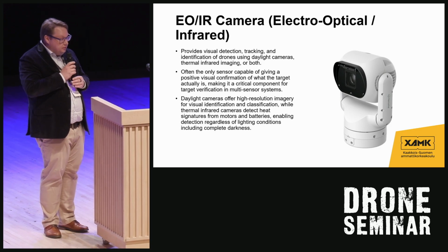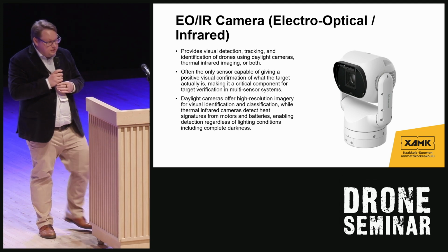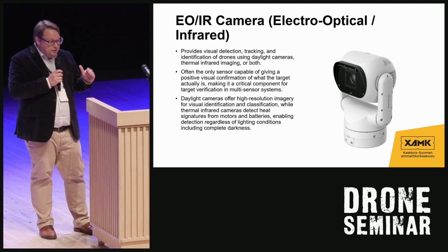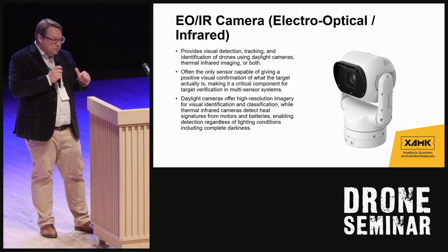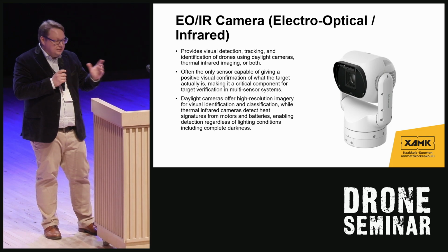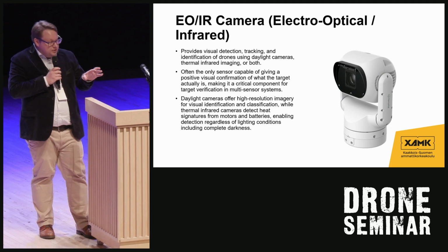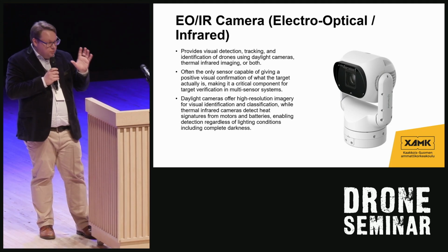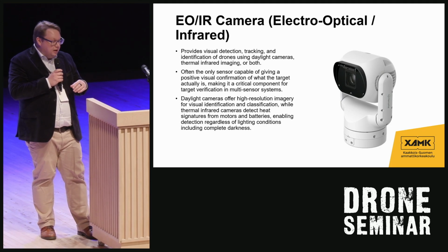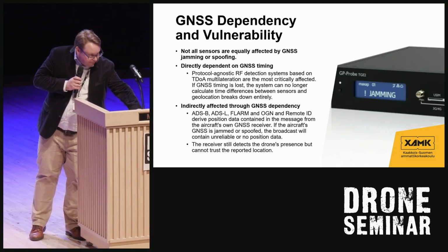Also, when you are building a drone detection system, you always need to understand what the threat is and what you want to detect, because if you want to detect everything, it will be very expensive. For example, a basic RGB camera is quite affordable, but a thermal camera gets a lot more expensive quite quickly.